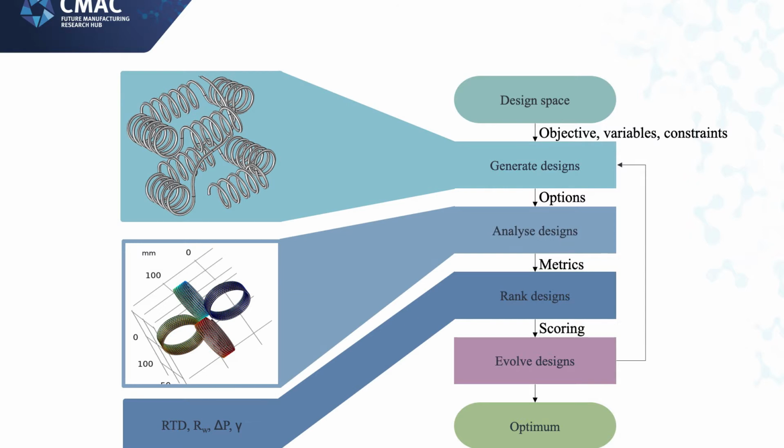So we've got up here a design. So this is a coil flow reactor. So essentially it's a bit of coil pipe that spins round on itself. And that is characterized relatively straightforward for a number of geometric parameters. So the diameter of the pipe, diameter of the coils, number of turns, layers, etc. So we can design these, and we can do these in CAD. There's a number of parametric approaches of designing these models.